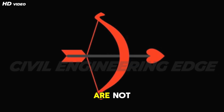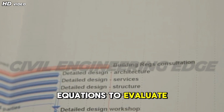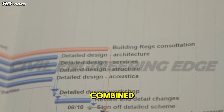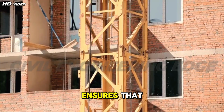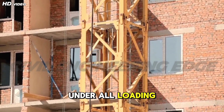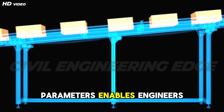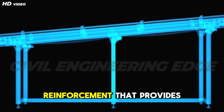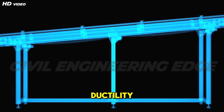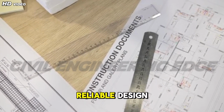These three parameters are not independent, they interact with each other. Design codes provide interaction diagrams and equations to evaluate column capacity under combined axial load and bending. Proper consideration of these parameters ensures that columns remain safe under all loading conditions. Understanding these key design parameters enables engineers to visualize force flow within the column and design reinforcement that provides both strength and ductility.